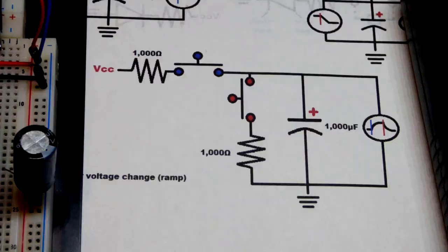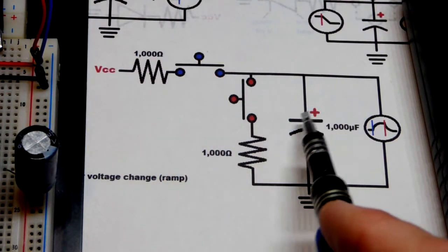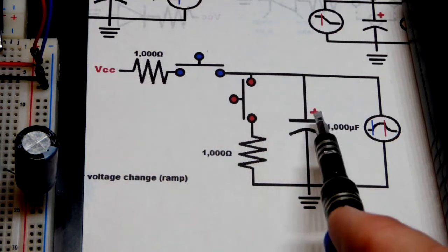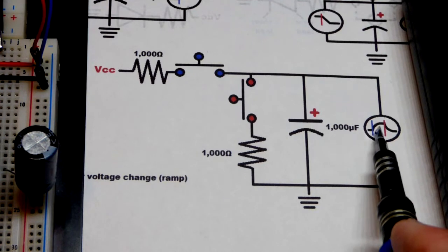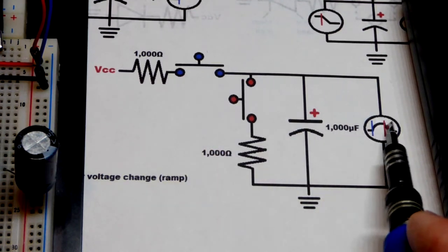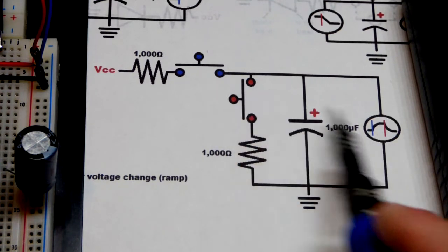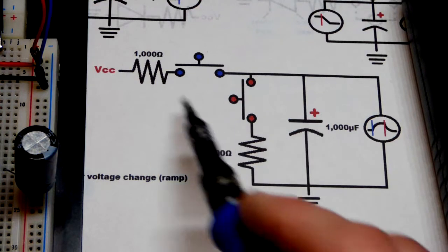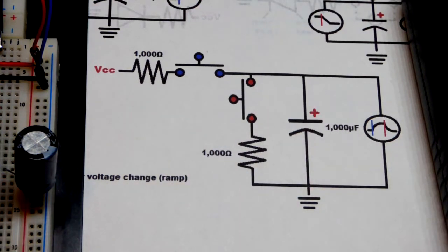So now that's it for this video. As you can see, we have the schematic there. There's the capacitor to charge when we press that button, and then discharge when we press that button. I put a little blue line there. That's when we press that blue switch right there that I just colored in blue. Hopefully you can see that. And then red. I put a red switch, when you press that one, it discharges. If you just hold them, then current will flow through the two of them. The capacitor will sit at half of the power supply voltage after it charges or discharges to that point.